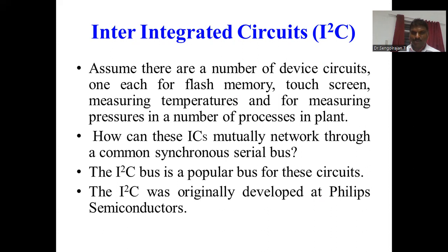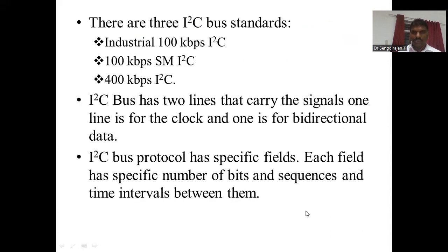It was developed by Philips Semiconductors. There are three I2C bus standards. One is the standard 100 kilobits per second I2C bus. Another one is the 400 kilobits per second I2C. These are the integrated circuit bus standards.